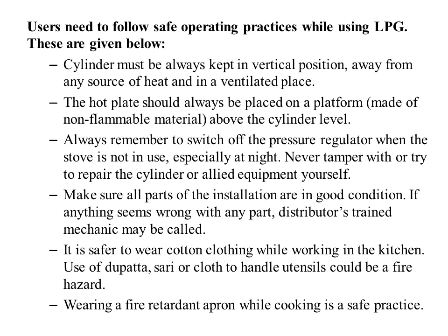Again, these are some of the operating practices while using LPG, that means how to install an LPG. The cylinder must always be kept in a vertical position, and of course it should be away from any heat source, and it is better to keep it in a ventilated area. The hot plate should always be placed on a platform above the cylinder level. And of course, when the cylinder is not being used, we should switch off the pressure regulator, especially at night. And we should never try to repair or tamper with the cylinder or any of the related equipment.